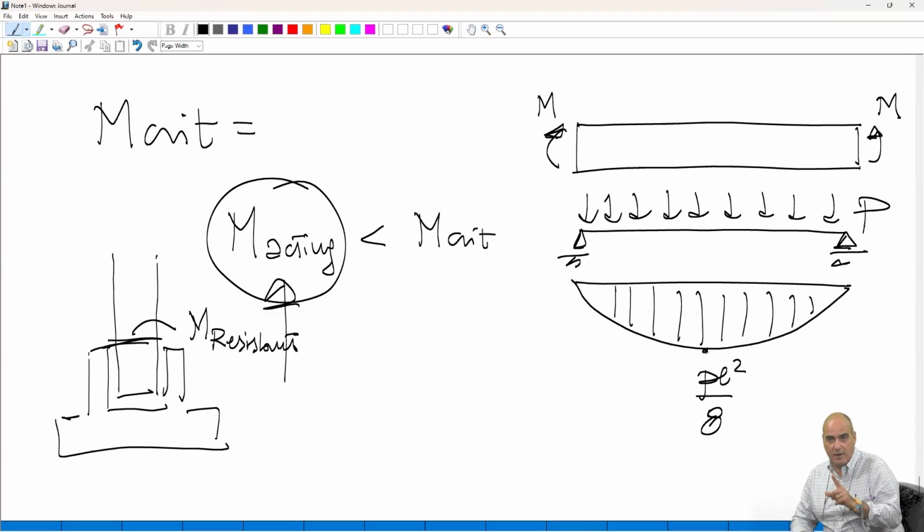Precast structures work reasonably well in seismic regions, and then you have to design the connections properly, because they have the stiffness which is appropriate for them. And they can dampen, in a sense, the effect of the ground motion. Their dynamic characteristics are such that they reduce the peak ground acceleration, and so they work more effectively. Over-designing may counteract these characteristics. So over-designing is not always the wise choice.